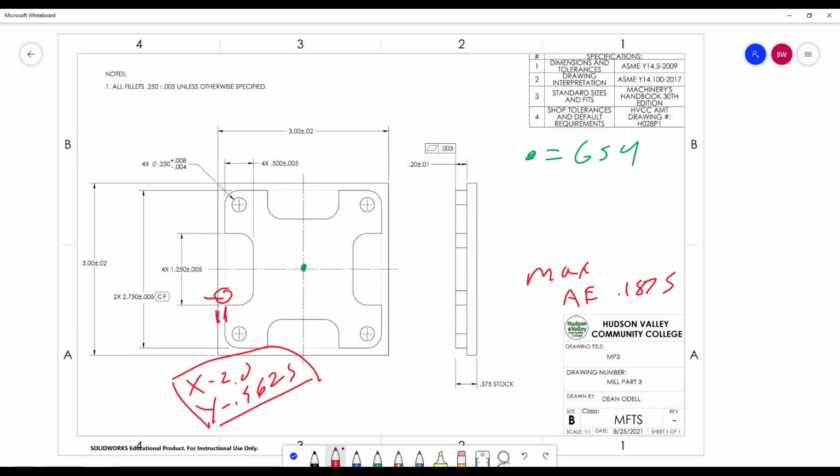All right, so we need to come in to take a 3/16 depth of cut. So here to here is going to be 1/8 of an inch. Okay, so it's going to be 3 inches minus 2.75 divided by 2 should be 1/8 of an inch. So we need to take that into account. So if we have 2.75, okay, divided by 2, and that's going to be 1 3/8. So this position here is 1.375, right? So 1.375, knowing that it's 1/8 of an inch from here to here, okay, again, we'll do the math. 1.5, half of 3, minus 1.375 is 1/8 of an inch.